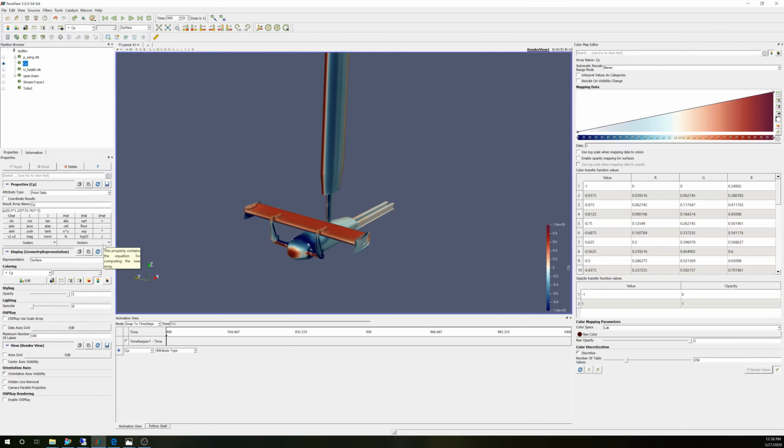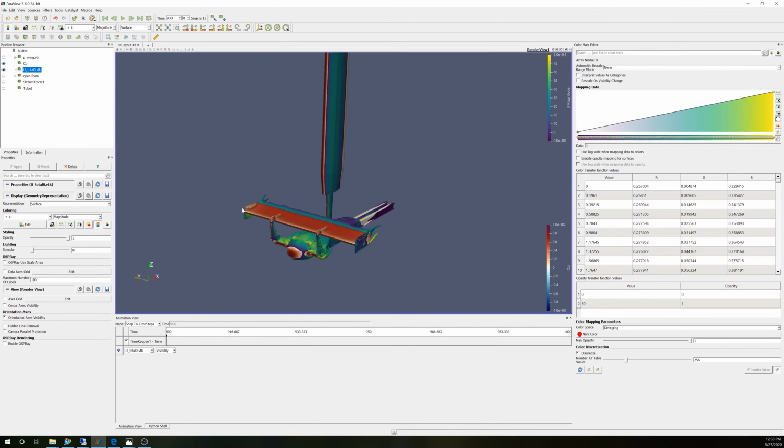One thing that we're going to look at that's a little bit different that we haven't looked at before is what's called an isosurface. An isosurface is basically capturing air, and it's putting surfaces all around the air where the total pressure is 0. It's really good for just seeing how the flow is coming off a bluff body.